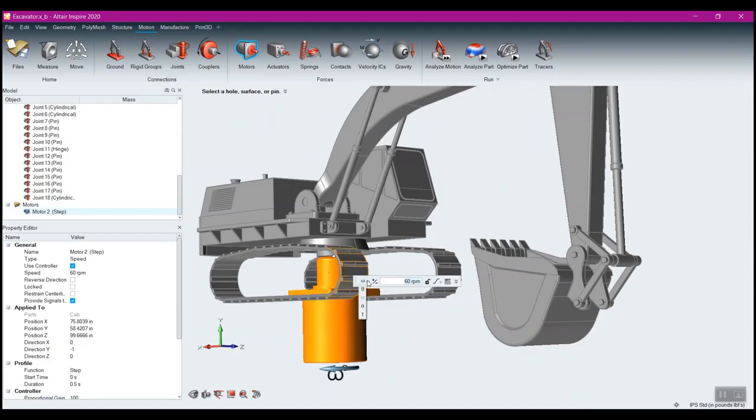And in the case of the motors, we have 4 different types of motors we can create, and the type of motor is defined by what its driving force is or what its driving aspect is. In this case, we have angle, speed, acceleration, and torque. So what do we want to be the driving factor of the motor? And it will achieve that no matter what any of the others is required.